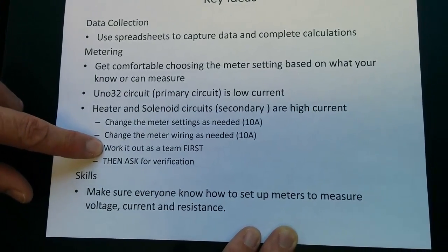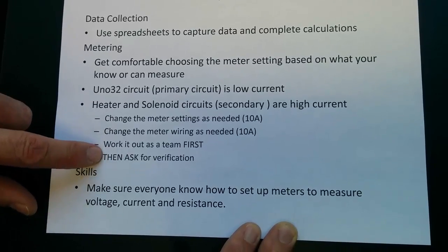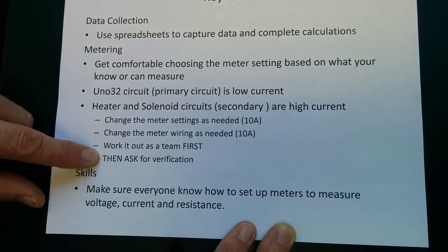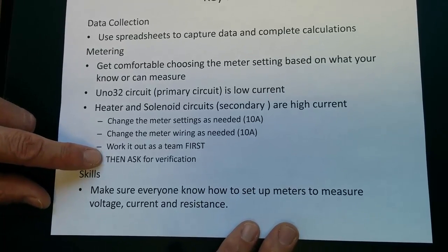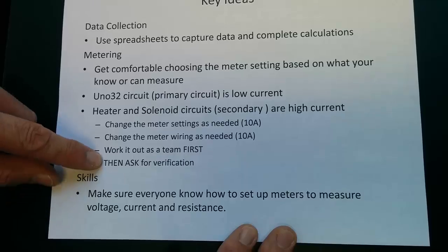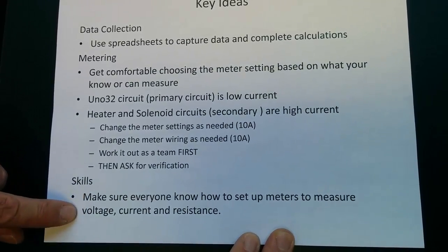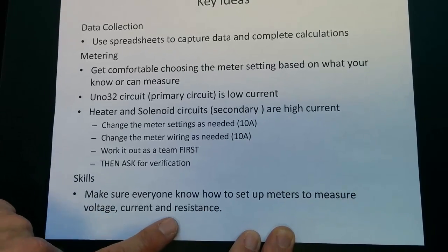I recommend you work it out as a team first and then ask for verification before you get started. We prefer not to blow as many fuses as we can, but it's an experience. Ask us first, and you can get reassured by us. Again, this is a skill. Make sure everyone knows how to set up the meters and measure voltage, resistance, and current.